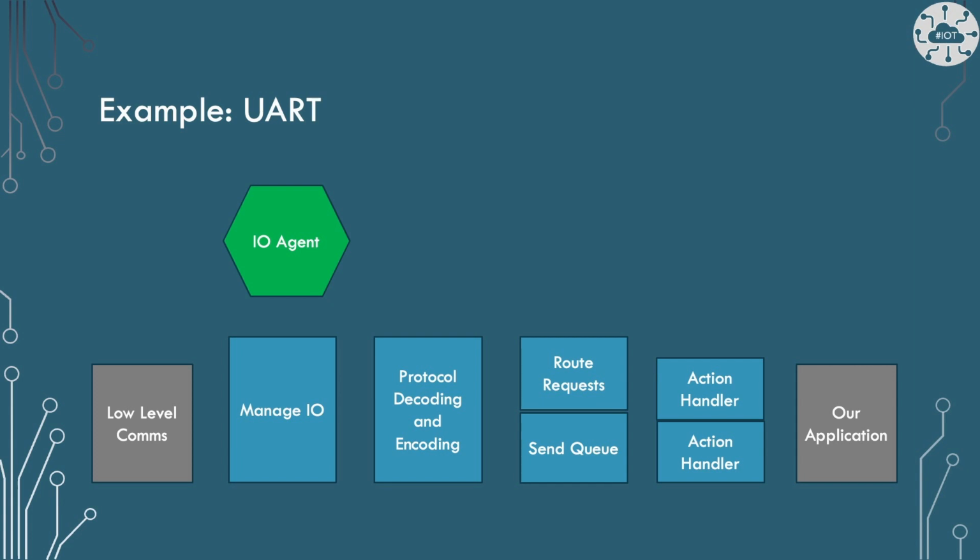Firstly, I will have an I/O agent that will manage the serial communication from the UART on the Pico. I'm going to use polling as a strategy in this example, as it's simple. That means that this task constantly looks for new serial data. When it has a whole message, a line in this case, then the message will be passed to the decoder agent. The decoder agent will decode the JSON and check it's valid, so it has the number to display.